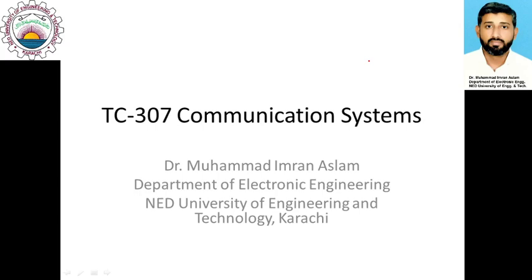We are now starting the third lecture for week number 10 of our course of communication systems. In our previous lecture, we talked about the binary baseband modulation, which is named pulse code modulation. In order to achieve pulse code modulation, we have to pass the analog signals through different processes, namely sampling, quantization and encoding, in order to generate pulses corresponding to the information contained in that analog signal.